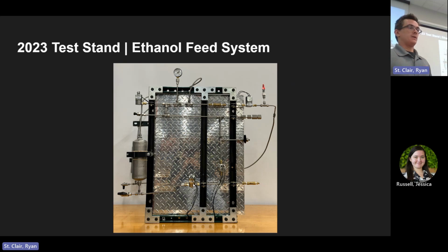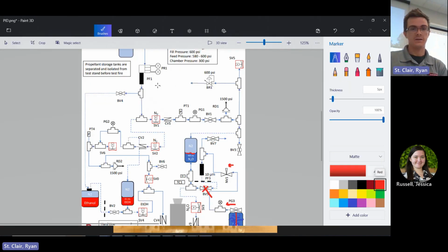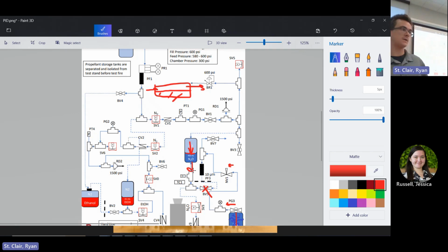It won't. Think of it like, what's a good analogy here? If you have a straw full of water and you start to blow on the top of it, it will blow the liquid out before it blows the pressure out, which is the air in your lungs. But to what you were saying, you do have to keep the tank vertical for that to happen. If you have a tank like this and your water line or fuel line is right here, if air is going in here, air is coming out here. There's no reason for it to push pressure out. So it's important to keep it vertical so that the pressure is pushing fuel or oxidizer through the system, and it's not just getting around it.